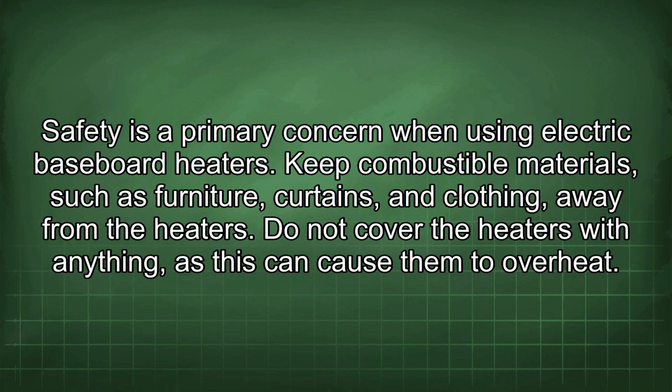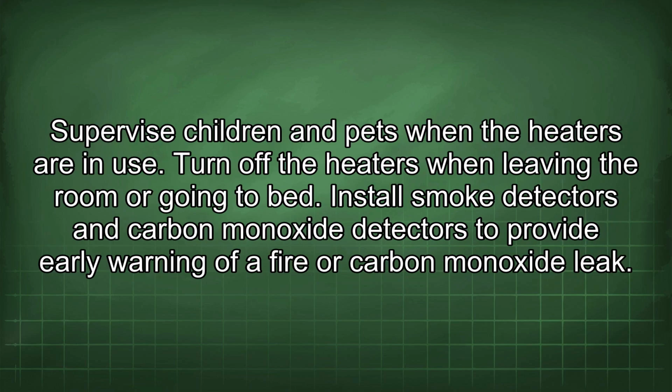Safety is a primary concern when using electric baseboard heaters. Keep combustible materials such as furniture, curtains, and clothing away from the heaters. Do not cover the heaters with anything, as this can cause them to overheat. Supervise children and pets when the heaters are in use. Turn off the heaters when leaving the room or going to bed. Install smoke detectors and carbon monoxide detectors to provide early warning of a fire or carbon monoxide leak.